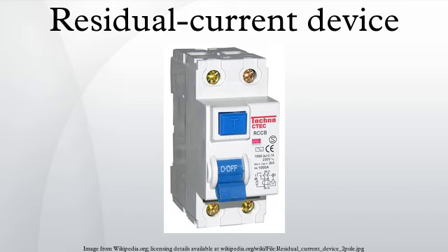In Europe, RCDs can fit on the same DIN rail as the MCBs, however the busbar arrangements in consumer units and distribution boards can make it awkward to use them in this way. If it is desired to protect an individual circuit, an RCBO can be used. This incorporates an RCD and a miniature circuit breaker in one device.